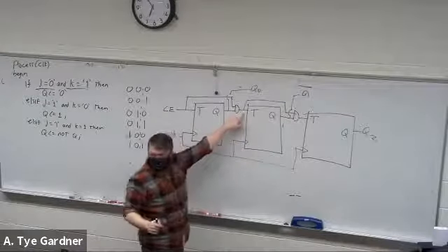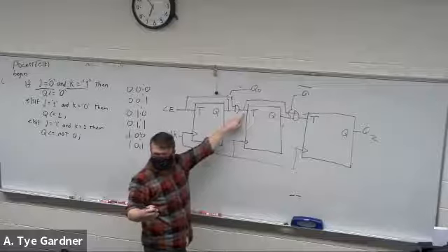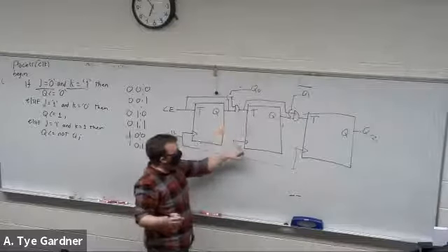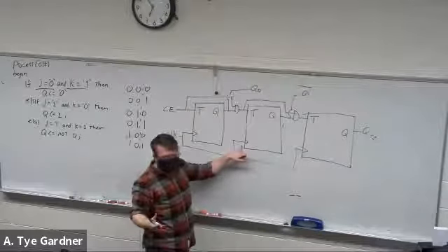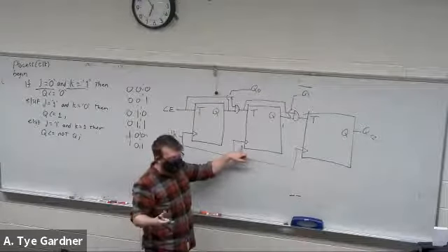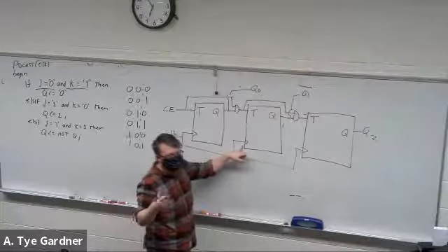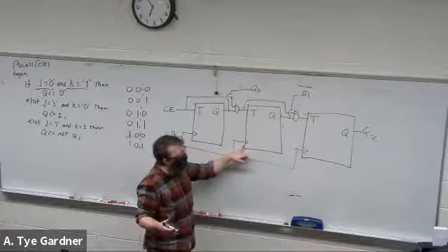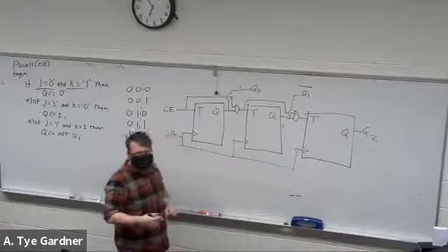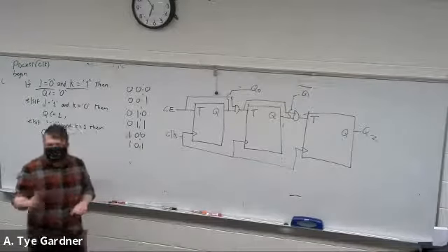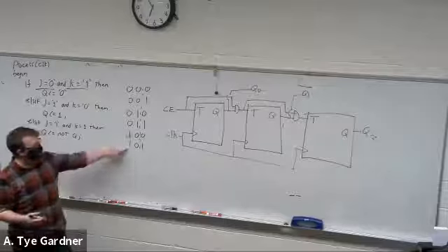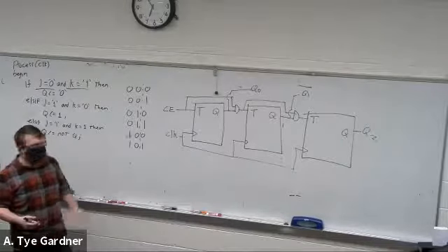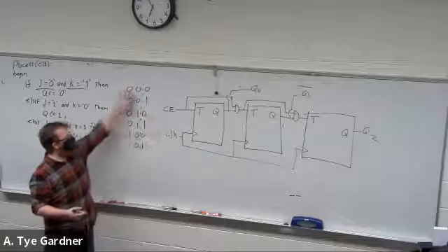But as we showed before with the clock divider, because that's switching here, we're only waiting until every other one kind of ticks along. So it's half as fast. And then the next one is half as fast as the previous one. So as they kind of march through this clock, we're just counting up. One of them is going 0, 1, 0, 1, the other one goes 0, 0, 1, 1.